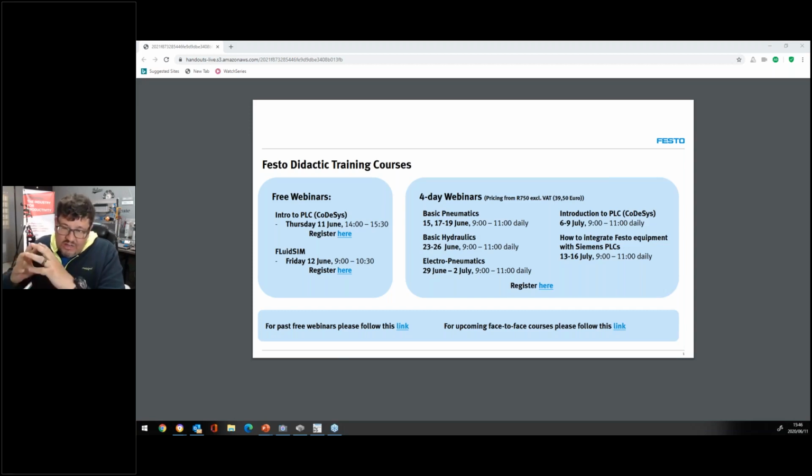And also, you must understand when it comes to the protocol. We talk about Profibus. Within Profibus, we talk about token passing. Maybe you know this. When we talk about token passing, that means on a bus there is a master and there's a slave. A master has permission to talk onto the bus, which means all the time he can send and receive data. Then you have what we refer to as a slave. A slave doesn't have the authority to actually request data. He only sends data.